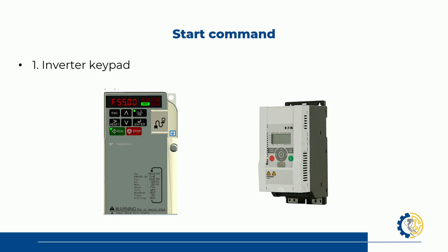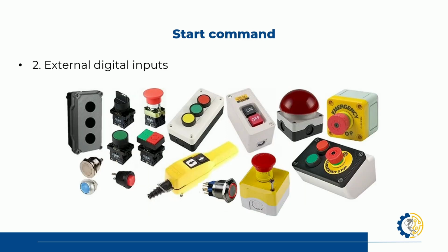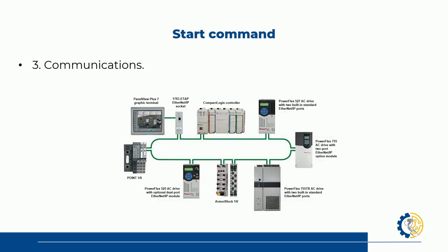So now what we need is to command the startup, which means where from am I going to command the startup? It's going to be through option number 1, variator keyboard, or external digital input, which is start stop, or the communication part.